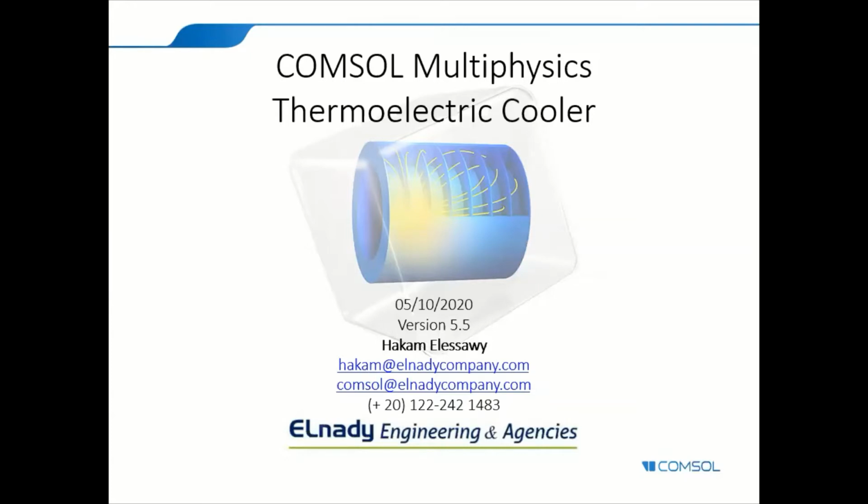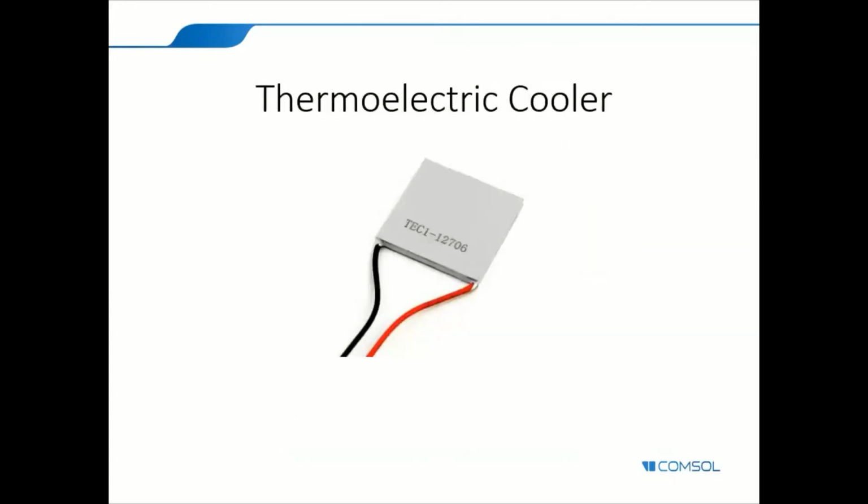So to begin with, we're going to talk about the Thermoelectric Cooler, or TEC for short. A thermoelectric cooler is a device made out of a PN junction semiconductor. When you apply a potential difference across the junctions, it's able to pump energy from one side to another. So you're cooling one side and pumping the heat to the other side. It can be used as a cooling device, in replacement of compressors with expansion fluid, like refrigerators and so on, in very tight spaces.